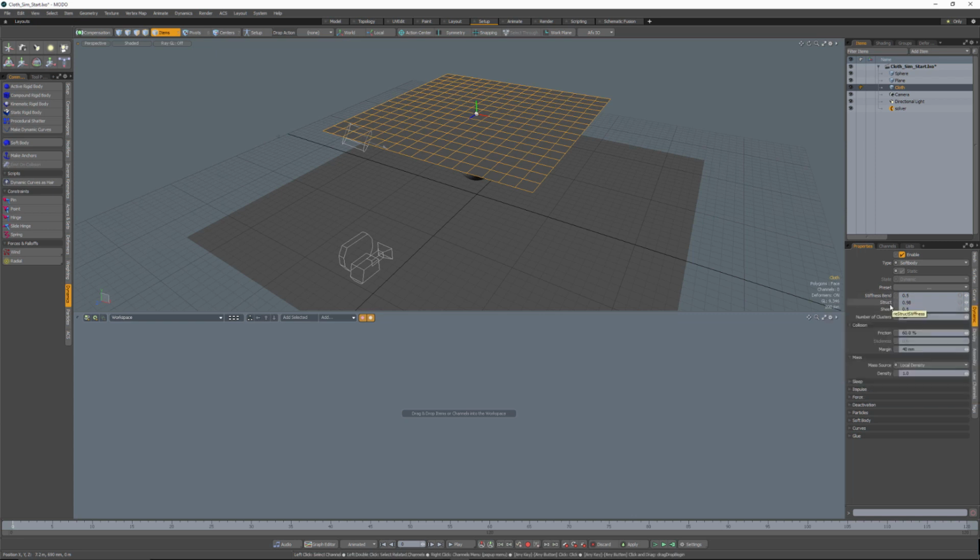The stiffness, struct, and shear, which we'll go over here in a minute, are defaulting to 0.5, 0.98, and 0.5. The number of clusters, that's essentially the resolution of the solve, is set to 16, which is pretty low, and we'll look at increasing that here in a bit. Friction is 60%, and margin is 40 millimeters.